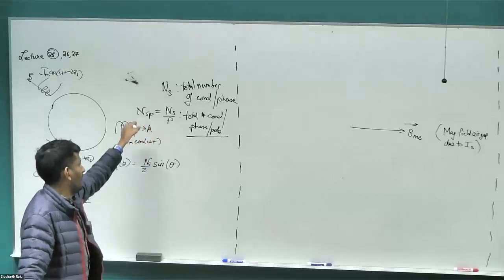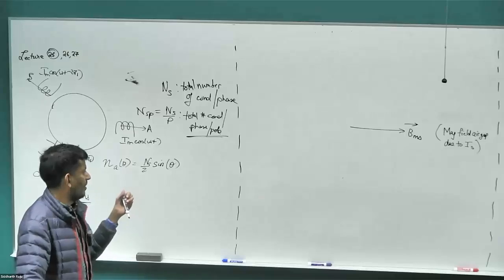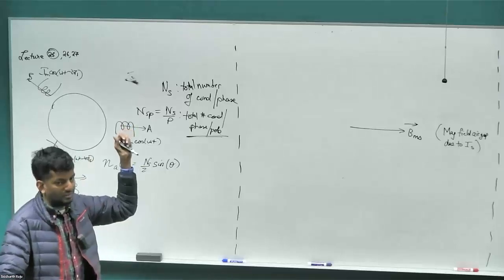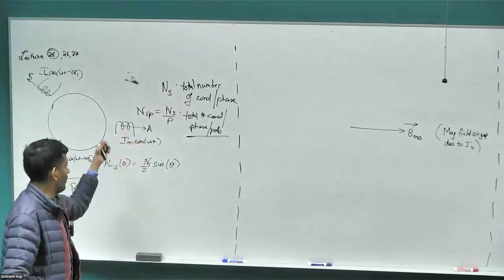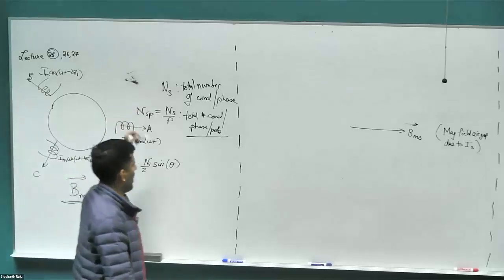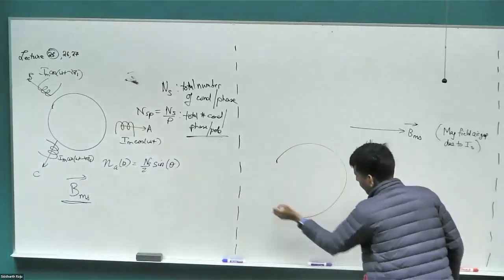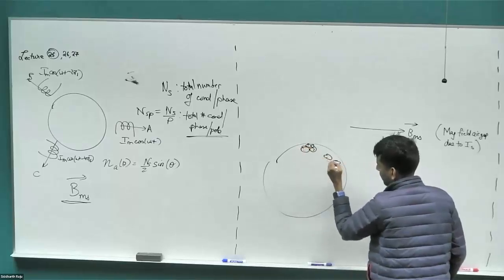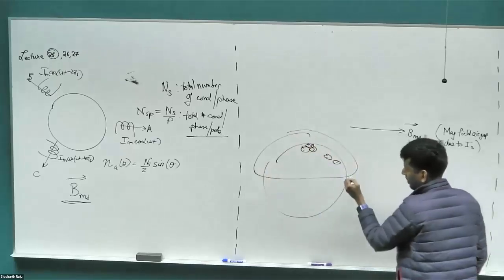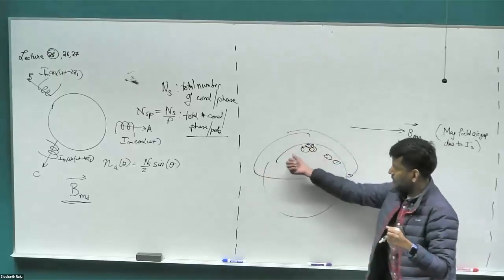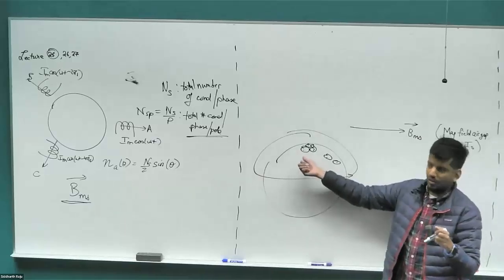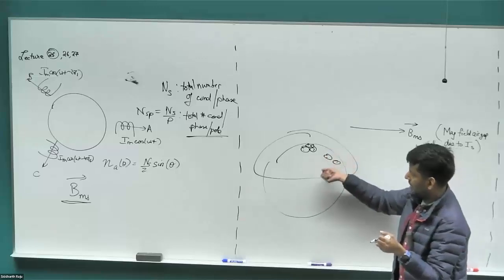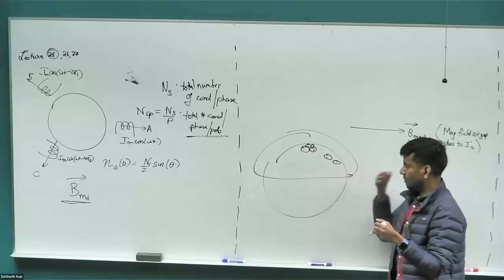Right, this is a useful notation because the common idea is, when you wind motors and go to a higher pole count, you would try to keep this NSP number the same. Because the maximum H field at any point in the air gap is determined by NSP. When we had our case of a two-pole motor with some 50 conductors in total here, the B field would have been decided by the total number of conductors within this section, which was 50. You would have had some mu naught times N divided by LG times the current. So this number of conductors determines what the peak B field is going to be.